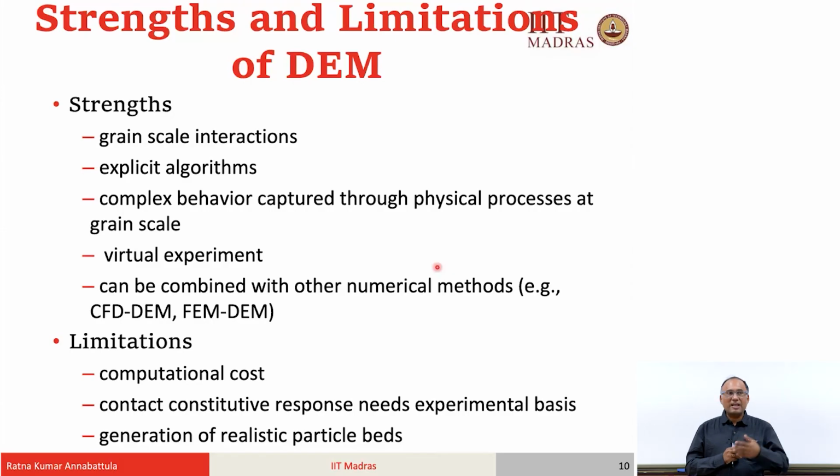And one of the striking features with the development of DEM over the years is that it can now be combined with other numerical techniques in order to enhance its capabilities. For example, you can now combine CFD and DEM, so that you can study particle fluid interaction and what happens when a particle laden flow takes place, how particles influence the fluid field and how fluid field influences the particle. Similarly, you can do FEM DEM coupling.